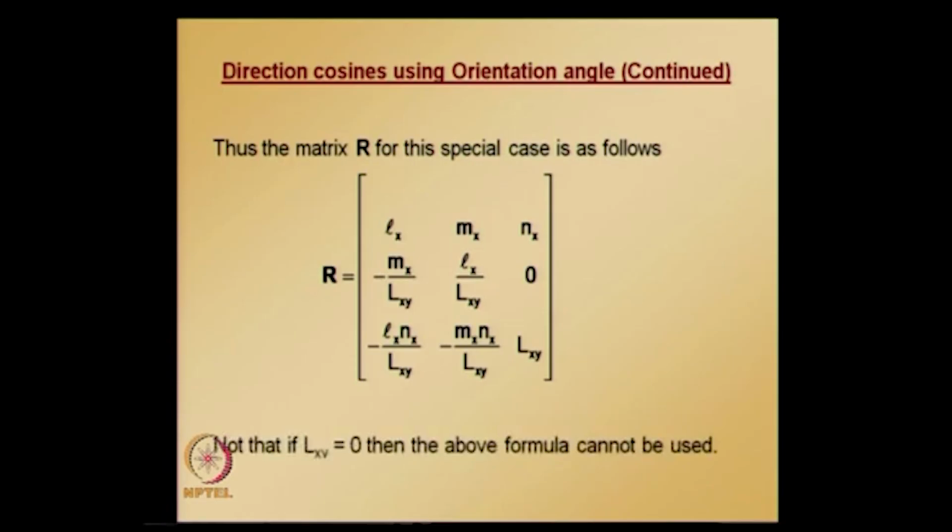Note that if Lxy is 0, then the above formula cannot be used, because Lxy is in the denominator. When you have something in a denominator, it goes to infinity. So, we will have a problem with this equation in calculating the rotation matrix. We will see under what circumstances Lxy is going to be 0.